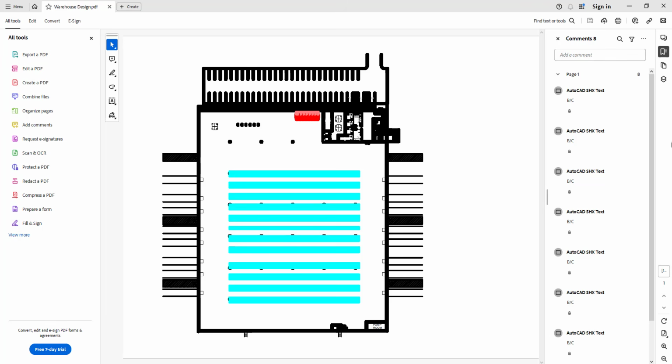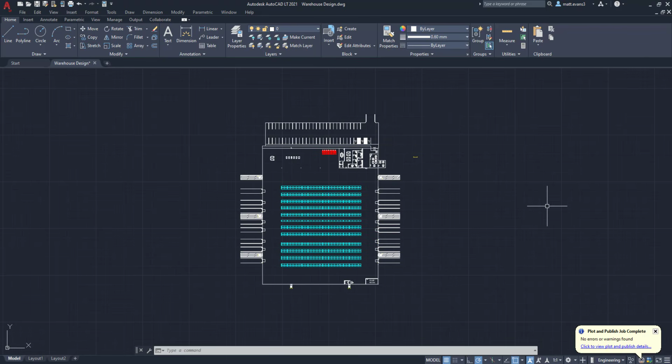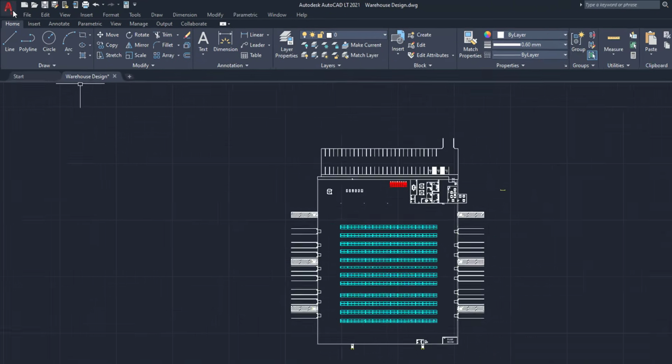So we're going to go ahead and close this out, and we're going to actually go into the next way to convert a DWG into PDF form. Alright, so to convert a DWG or AutoCAD drawing into a PDF without the line weight of the lines in the drawing being all funky, you can either go through and find all the lines that are bad or not the right size, the line weights, or you can come up here to the same AutoCAD button.